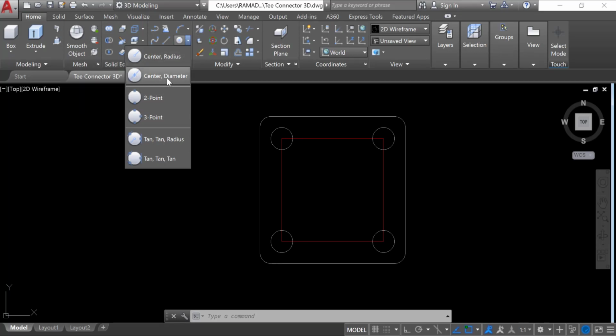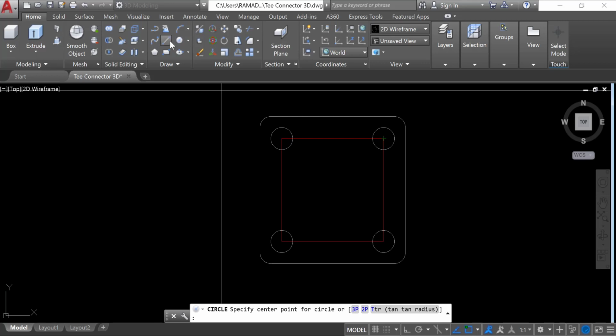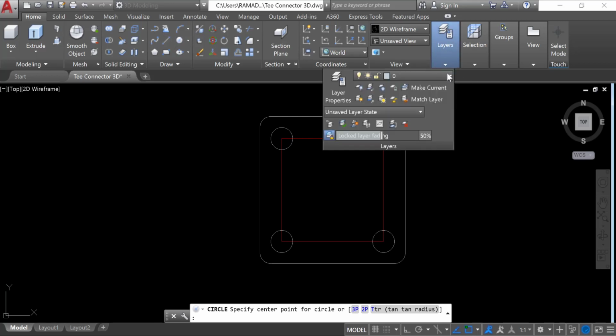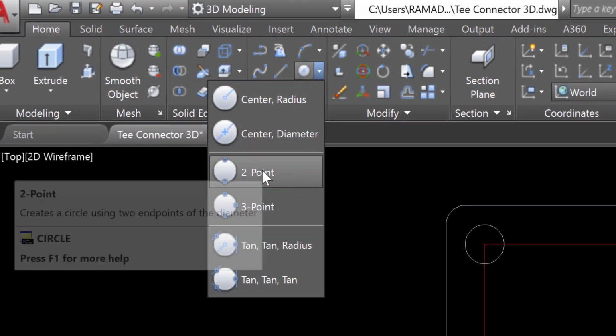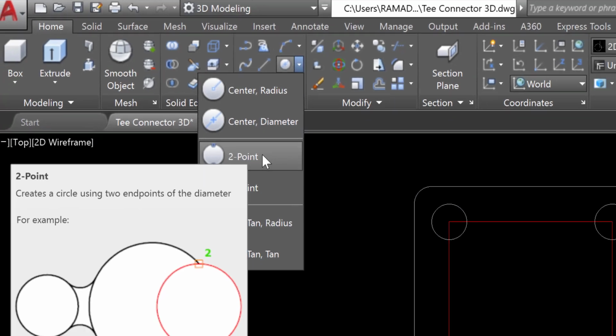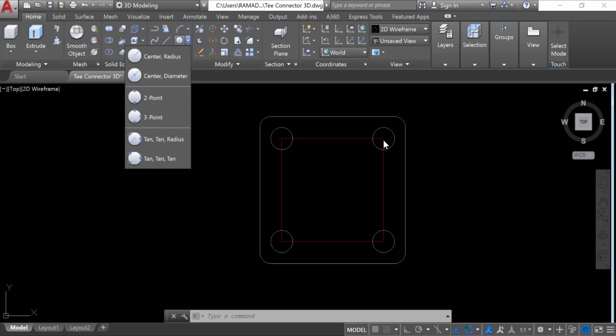Here there are two decisions you can make. Go to diameter, and then first you have to draw a center line. Let me show you a trick first. Go to circle. This is the method of drawing a circle. We know the distance from here to here is 140. So it means that if we need a circle to have 140 here, we need either to draw from the center of this line, or the circumference has to touch here and here.